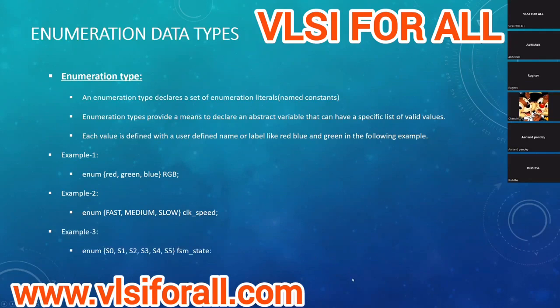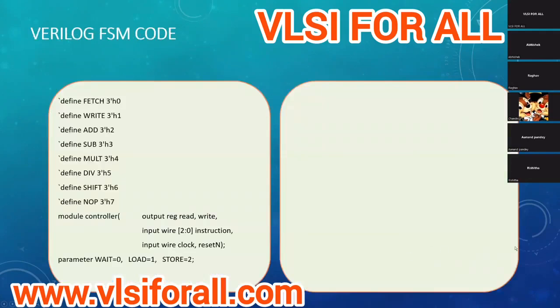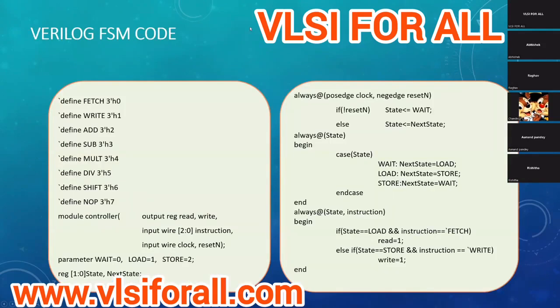Yes, this is another example. We'll look at one FSM code quickly and then I'll wind up today's session. We don't have much time, only 6 minutes left. Consider these defines. We have used multiple defines here: fetch, write, add, sub, mult, divide, shift and nop, and we have given different values to them. A define is a way to give a name to different values. It's another way of doing what an enum does.